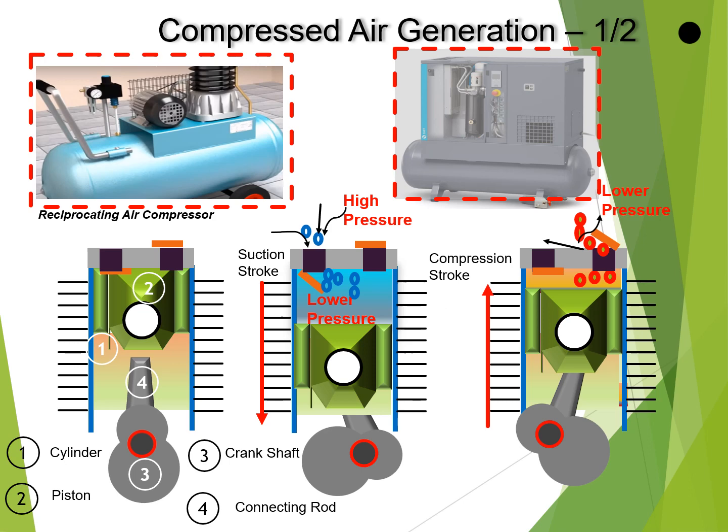It is then passed through intercooler which removes the heat of the compressed air. Then it goes into the second stage where it is compressed to 8 kg, the desired pressure. So the temperature is also reduced, the pressure also better managed. Whereas in a single stage compressor, we will have to compress the air from atmospheric pressure to 8 kgs.